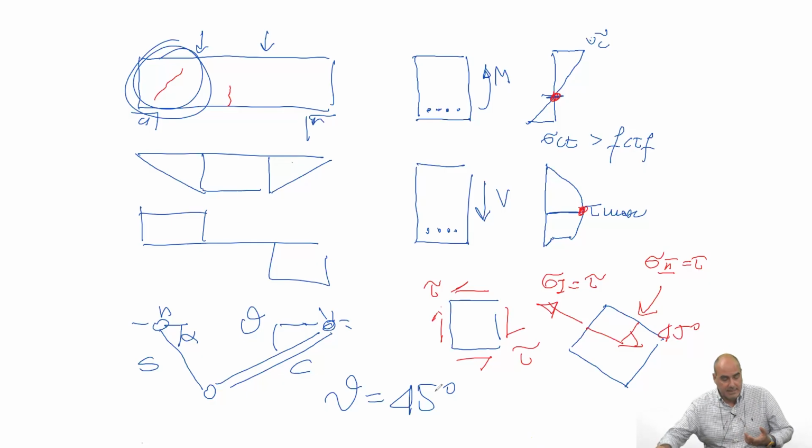What has then led to use a slightly different model? Because it has been realized over the years that this led to a little bit too conservative design. So the actual load bearing capacity of the beams was much higher than what you could predict from here. So if your model estimates a lower bearing capacity, it forces you to put more reinforcement.